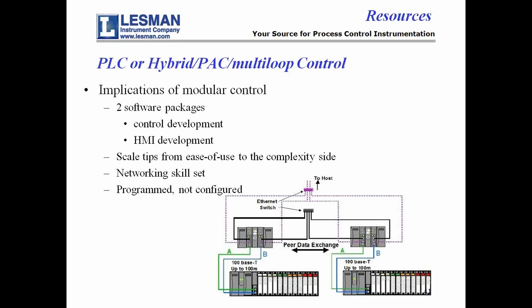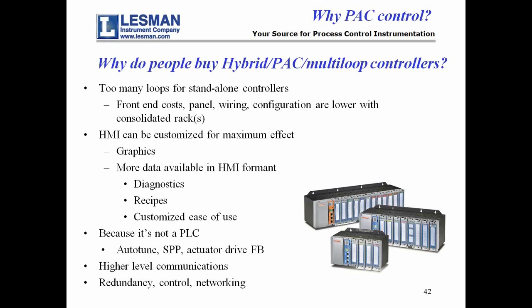The other thing you got to be aware of is that when you start doing this and you're talking over a network, like you can see all these little purple and green and blue lines out here, the communications network ties all this stuff together. There is some networking skill that's involved in this as well. So people buy PACs because basically there's too many loops for standalone controllers, but you want to be able to manage this data. And the HMI gives you the tool to manage the data, gives you your picture or your view into what the process is doing.